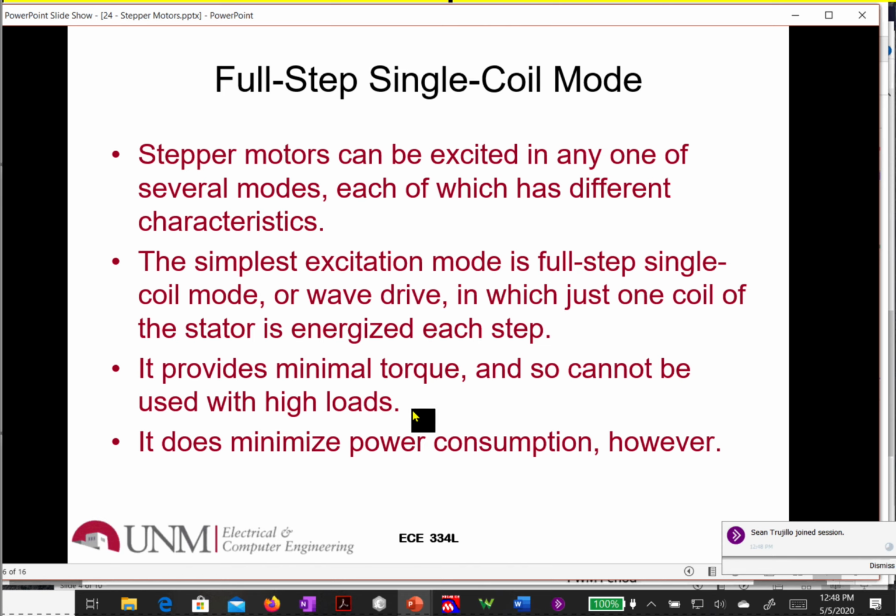Yes? Is the armature or the stator the moving component, or does it depend? So the armature is a rotating component, and the stator you could think of as the housing. I have windings in the stator. So if I have a magnet in my armature, and then I energize windings in the stator, then I'll have repelling forces which will cause it to move.